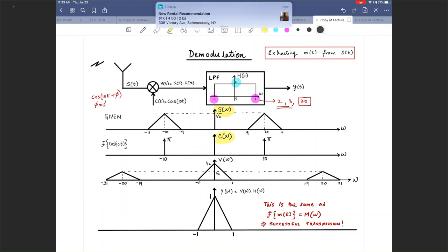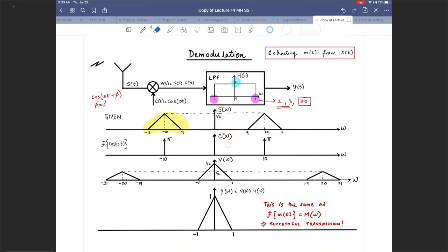The first piece is going to be this triangle convolved with, oh, come on. This triangle, let's see, erase this and erase this. The left triangle convolved with an impulse, right? What do you get? You get that guy. That's your first convolution, because you can break this up into 4 convolutions, right? Left triangle, left impulse, left triangle, right impulse, right triangle, left impulse, right triangle, right impulse. So 4 convolutions, but all those convolutions are with impulses, delta functions. So frequency shifts, that's it.